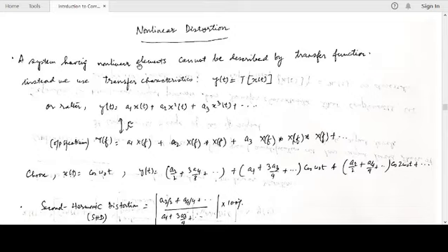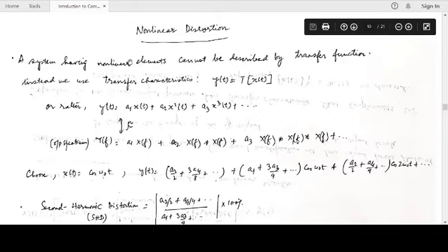In recent days we do some kind of reconfigurable antennas. That means the antenna parameters or the filters change with frequency or adapt with the frequency, or in the channel environment, the beam is steered in various directions. So naturally they will have nonlinear elements to control. They will have transistors, they will have several kinds of diodes to control the behavior or reconfigurability. So these are known as nonlinear elements.